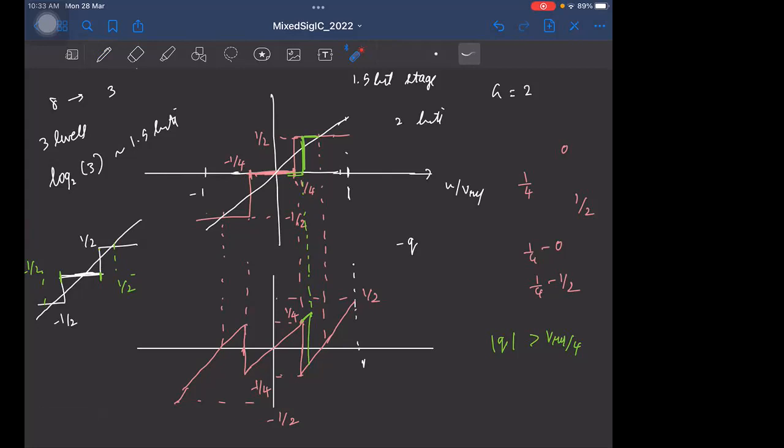So here, if there is any error in the comparator threshold, the quantization error is just above 1/4, right? So if you use a gain of 2, it's going to be slightly greater than 1/2, and that is still okay. Okay. And in this case, can you tell me what is the maximum error you can tolerate in this error? That is this guy.